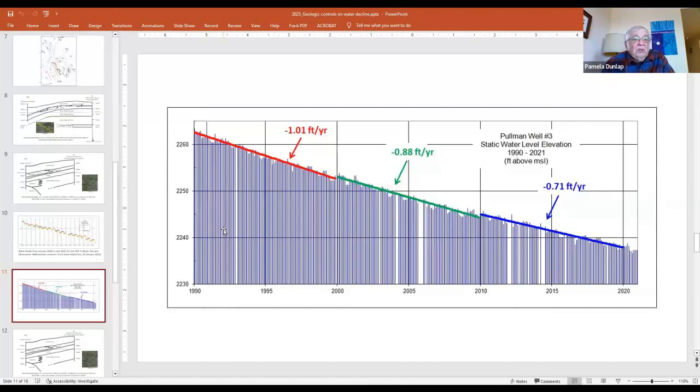And another possibility is some hydrologists will tell me that in other areas of the world, there are documented areas where, as you pump the water levels down, it causes the recharge to increase. So some people would say that as we have been pumping this area for so long, pumping this lower level aquifer, the lower water aquifer, for so long, that we are causing an increase of recharge around the basin. That's also a possibility.